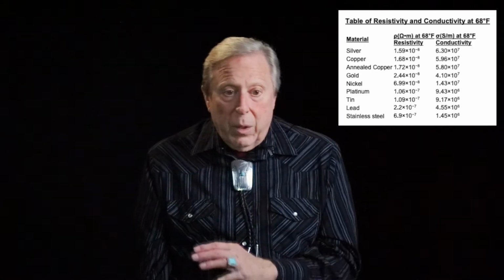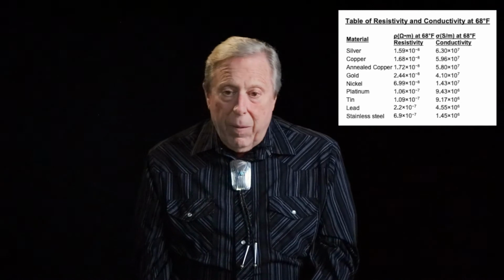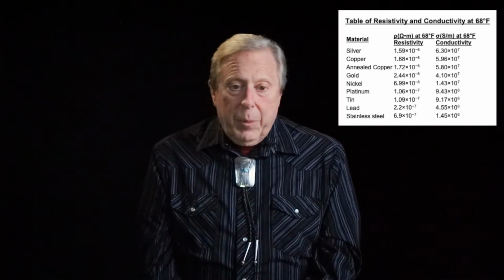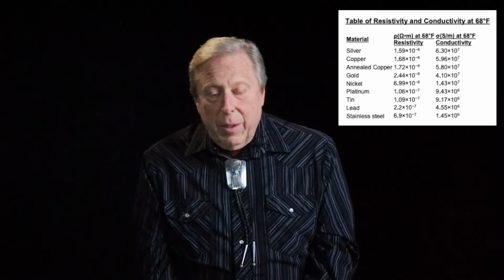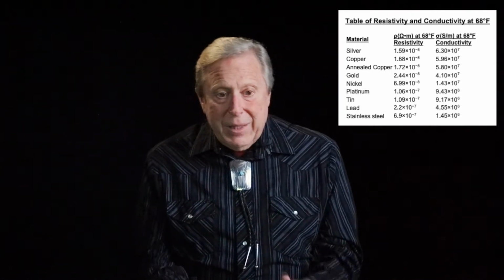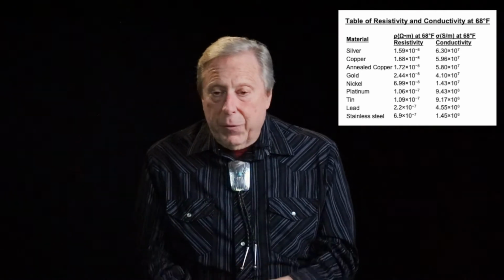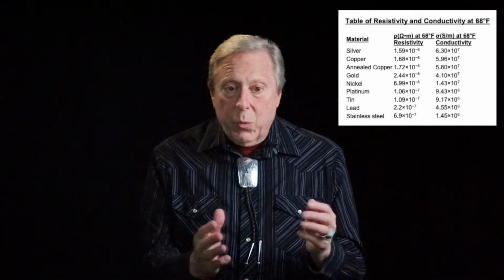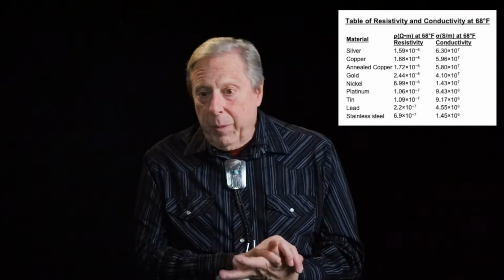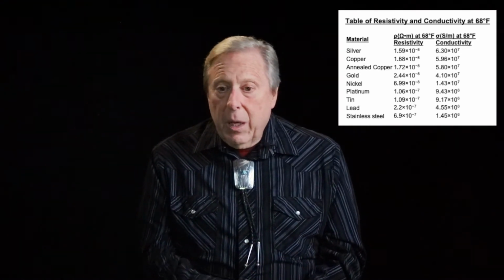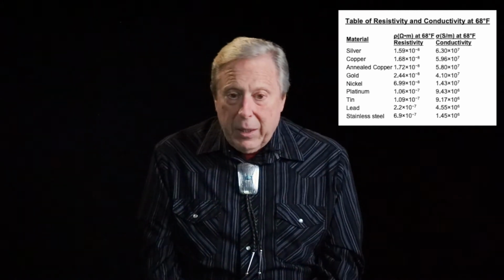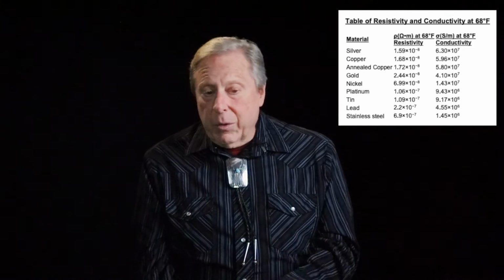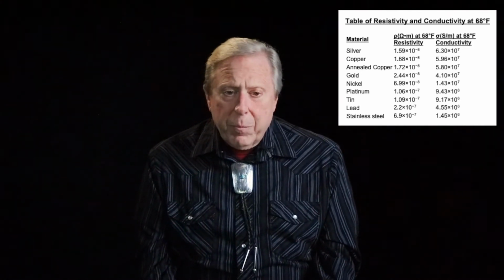The one we want to talk about is stainless steel. Now, stainless steel is great if you're building a structure, a knife, or parts for your car. But stainless steel is lousy for temperature control, and it's 200 ohms, so it's really lousy to make shield material out of, because a shield has to be less than 2.5 milliohms per the Mil standard, and you'll never get there from here with stainless.